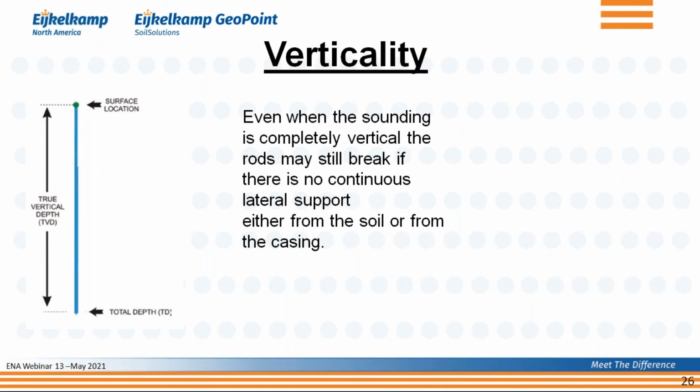So if you are in a place or in a condition where there is no lateral support, because you go through water or very soft soil, then please make sure that you don't rely just on the verticality. Make sure that you provide that lateral support as well by placing casing.